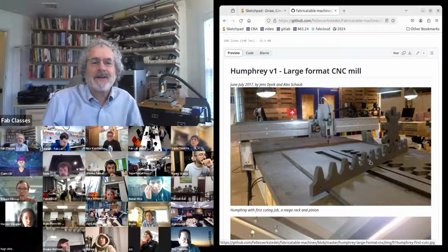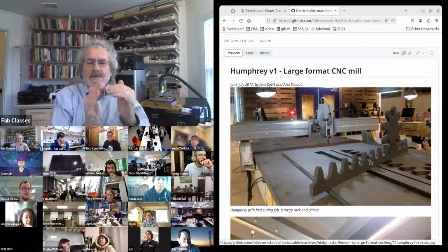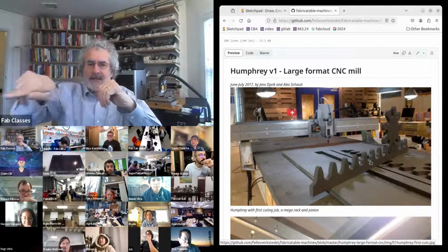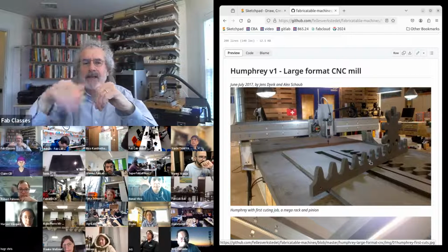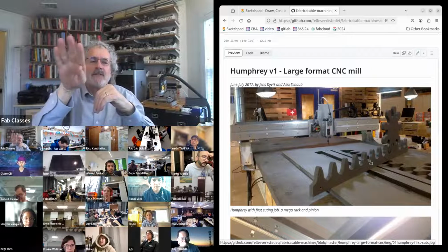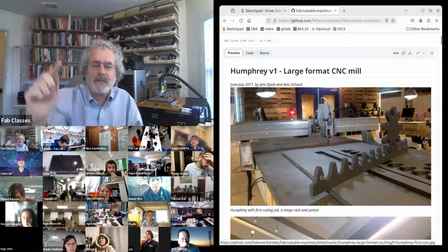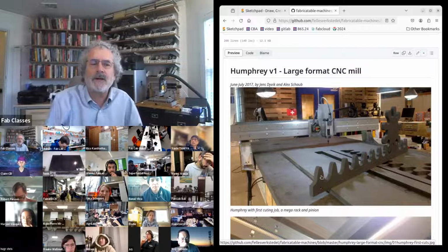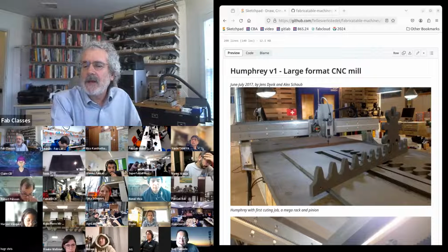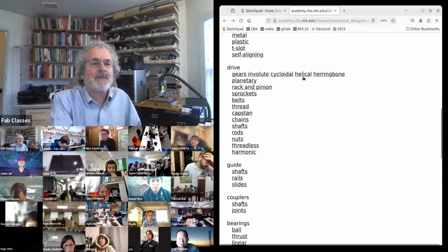I'll check with Jens. The reason for cycloidal is, with the involute, when the gear pushes, the pushing is closer to in plane. The cycloidal, the rolling shape, pushes at a higher angle, which is less good structurally. But what's nice about it is there's more clearance in here for the milling machine to get in and make the gear. So the cycloidal aren't quite as good structurally, but they're better mechanically. I'll confirm with Jens on the cycloidal.